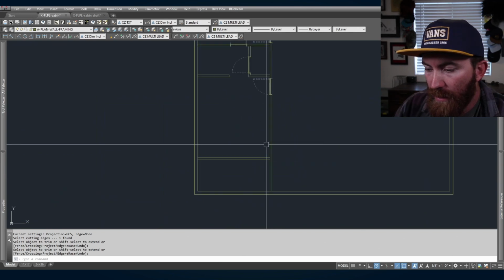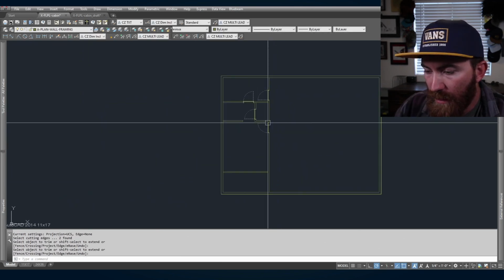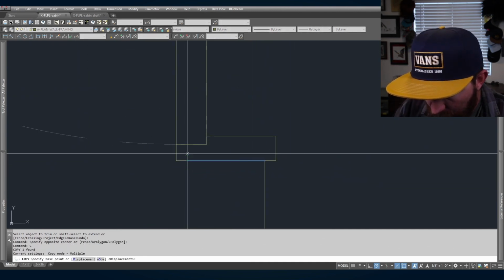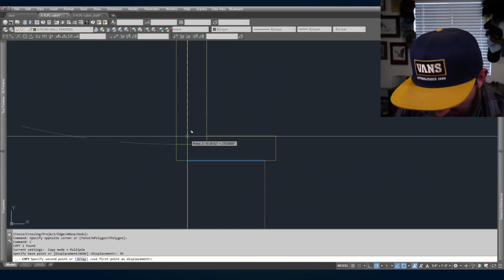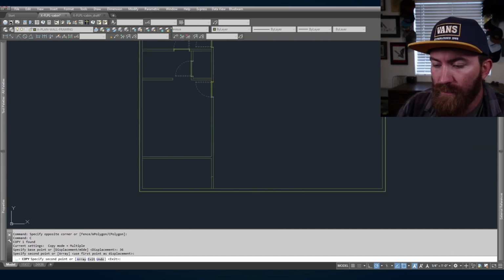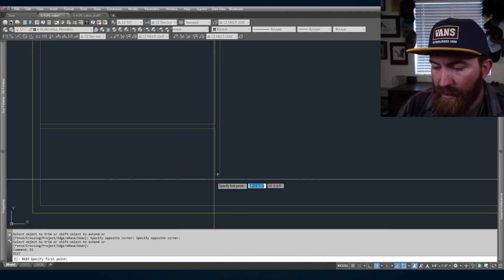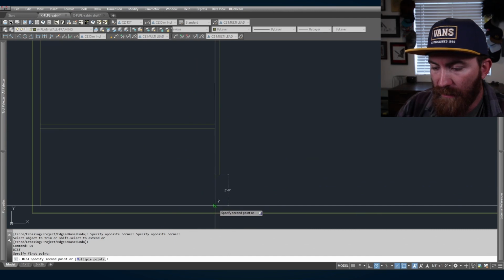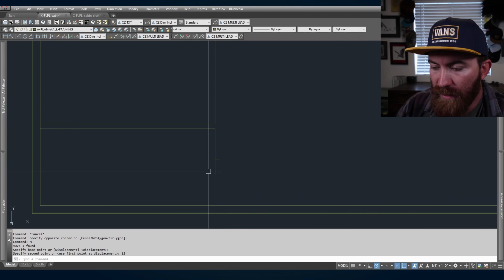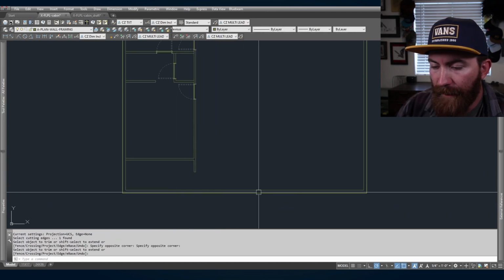Okay. I'm going to go ahead and trim this. I want to go ahead and copy that 36 inches away from that point, trim it. So this should be, and it's not, I did it wrong, 2 foot. That's interesting. So I just need to move it 12 inches. Could trim it, boom, look at that.